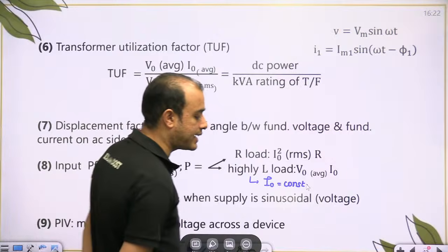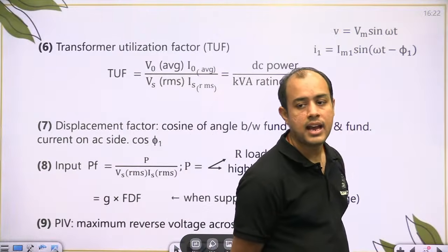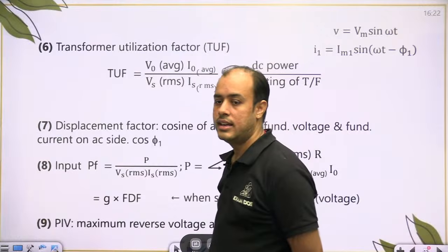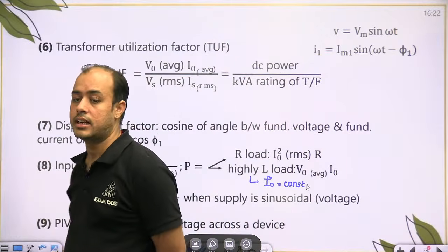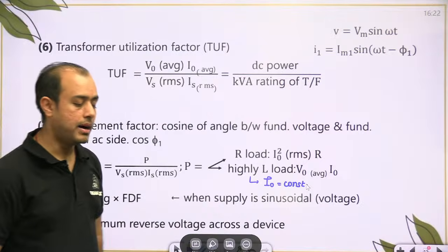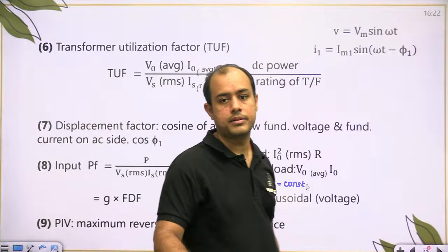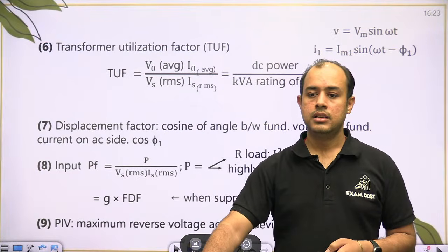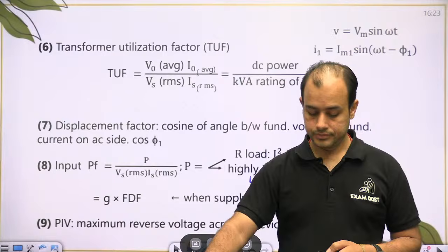पॉइंट समझ में आया? RMS cannot be directly added for different harmonics. RMS are added like root A square plus B square plus C square. That is why harmonic RMS is under root of total RMS square minus fundamental RMS square. Okay बेटा? Is this clear to everyone? समझ में आया सभी लोगों को?